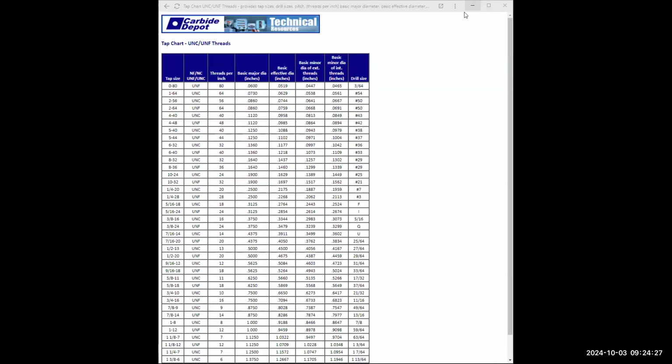Turn off F8, hit F8, click, turn F8 back on just for a second to make it a straight line. Click, enter. Now we're going to make this percent C space 0.38 through enter again. That's the first part.